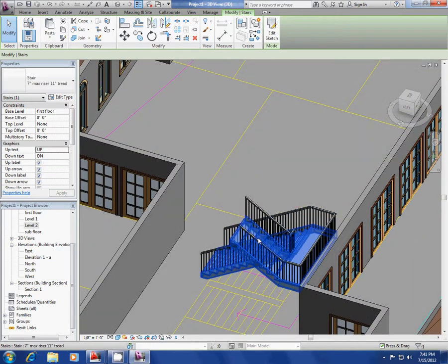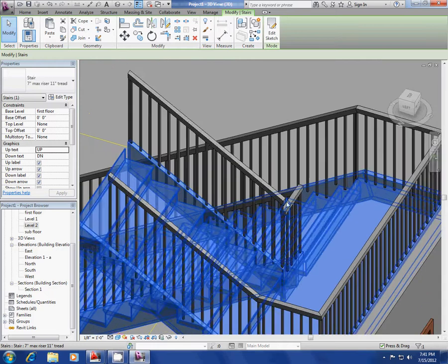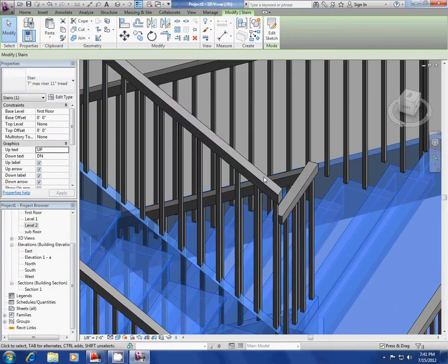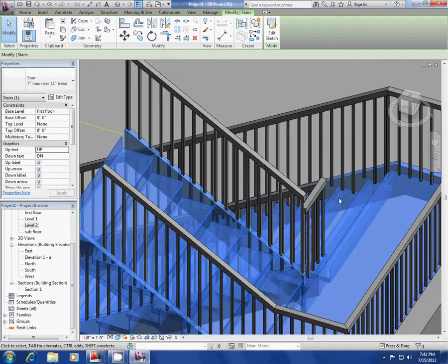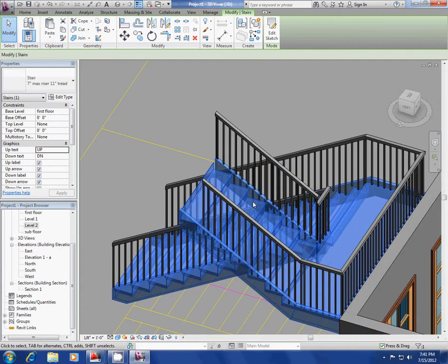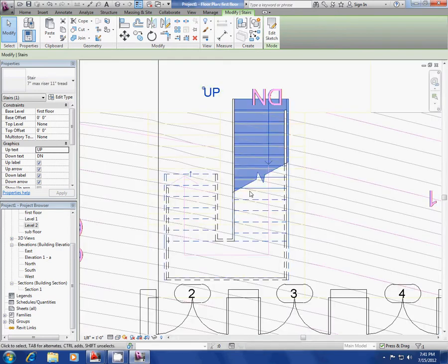Like I said, this is pretty simple to develop, but then you'll start to see, well, this handrail doesn't connect here, and this handrail doesn't connect here. It's not a smooth transition. And that's where the difficulty in stairs in Revit comes. You'll have to move those treads back until it meets those so that they're smooth. And it's just a matter of moving that line work around.